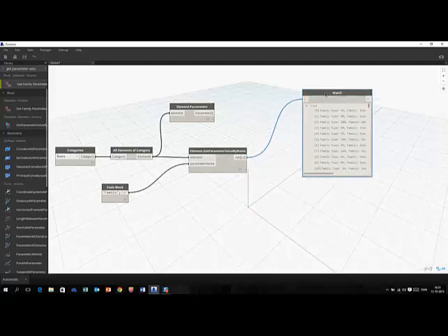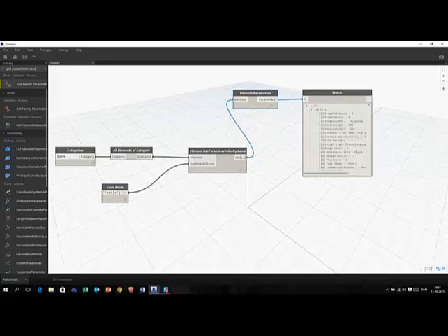Now I have the information about the family name or type of the door itself, and if I bring these family types into my element parameters, then you will see that my list of information has now changed. So the information I'd like to get out now would be the function, since the function is the information that I'd like to check on.